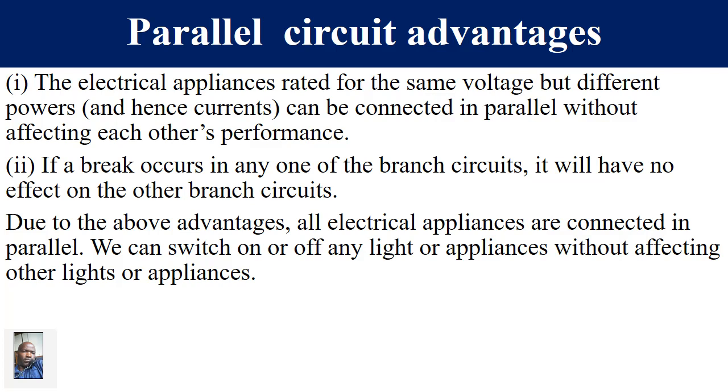For example, if a bulb in one of the rooms blows, it does not affect the bulb in the other rooms. Because of those two advantages, electrical appliances in our homes are connected in parallel. We can switch on or off any light or appliance without affecting other lights or appliances. Please take note.